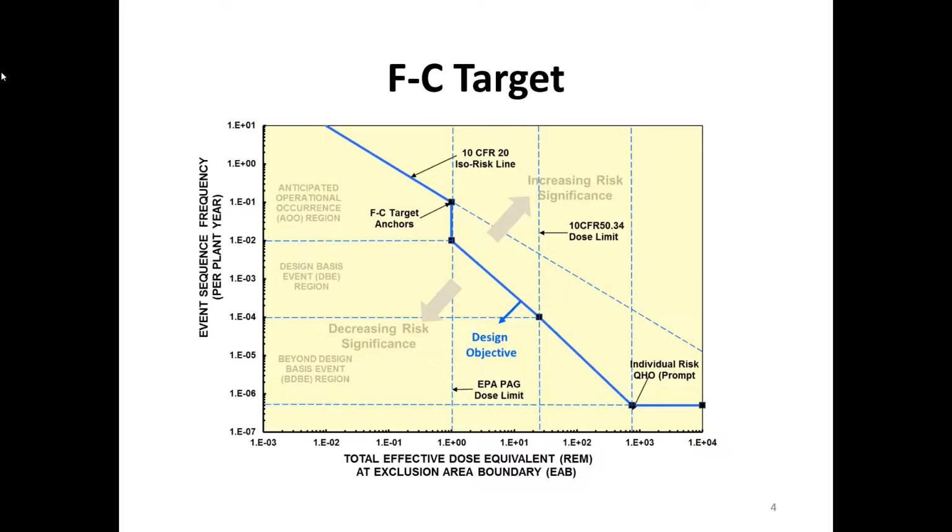So that's a good question, and I'm glad you asked, because there should be, once you determine the design basis earthquake. For example, SDC5 or SDC4, I determine what should be my design basis, and I decide whether I want, for a structure, an elastic limit, or I want to permit certain inelasticity. Those are the two critical decisions made based on this process.